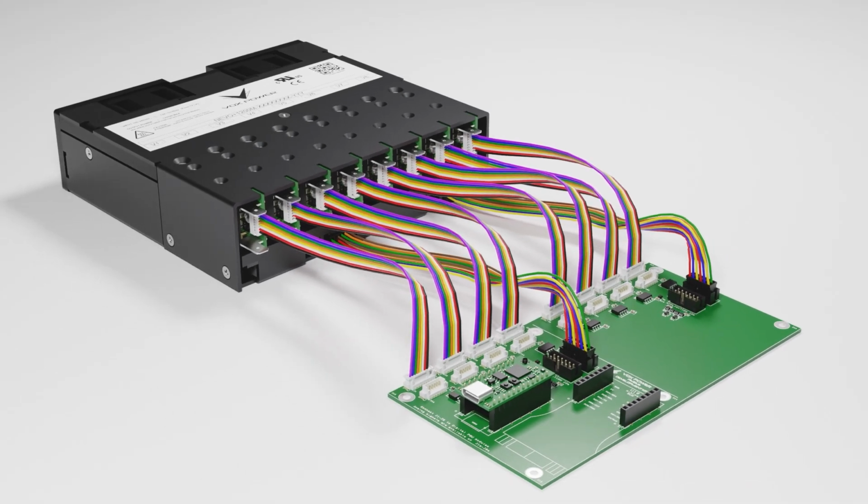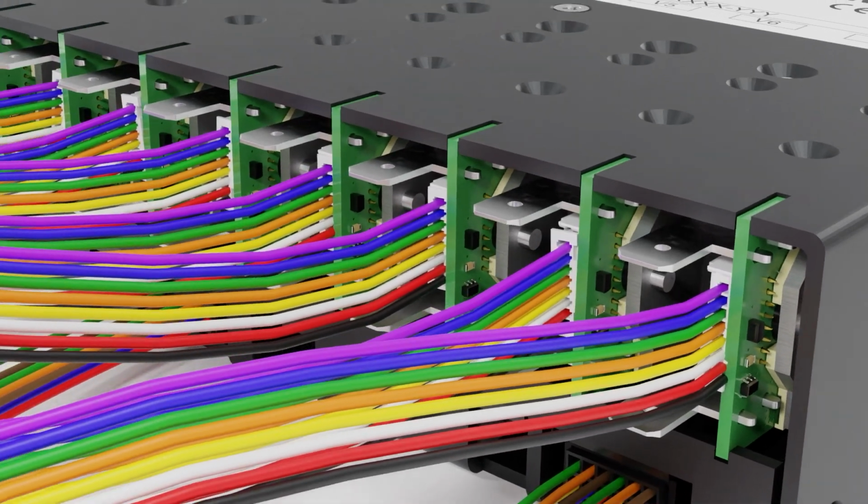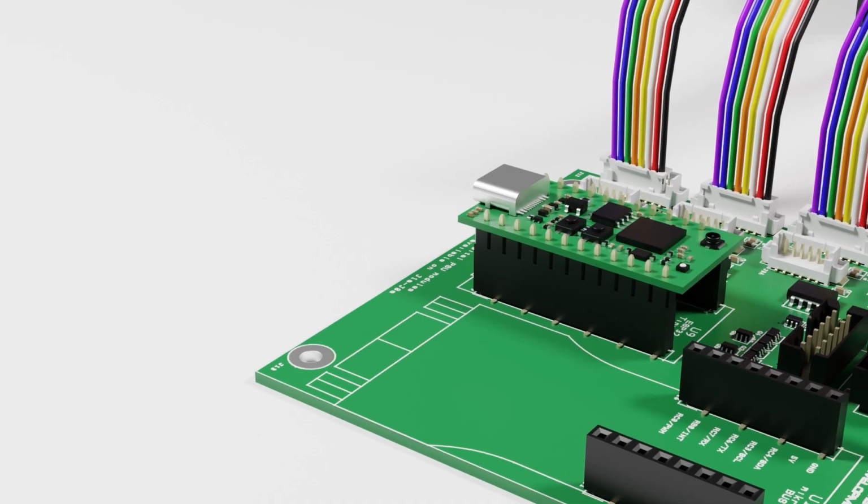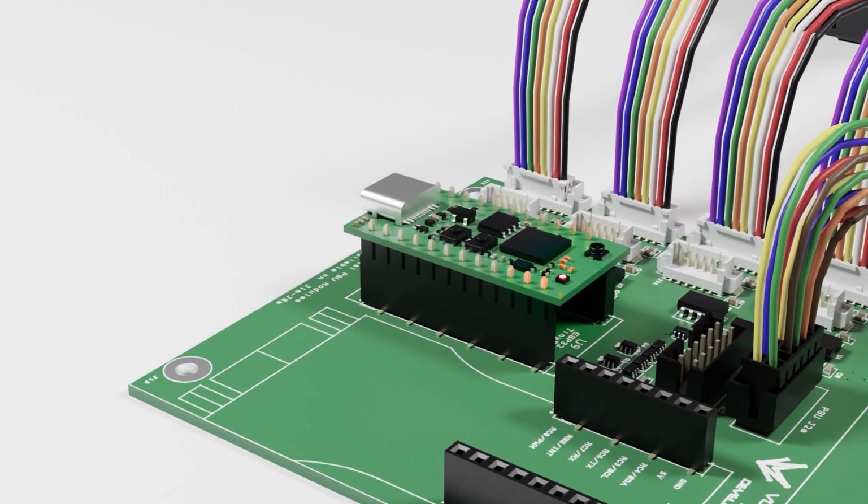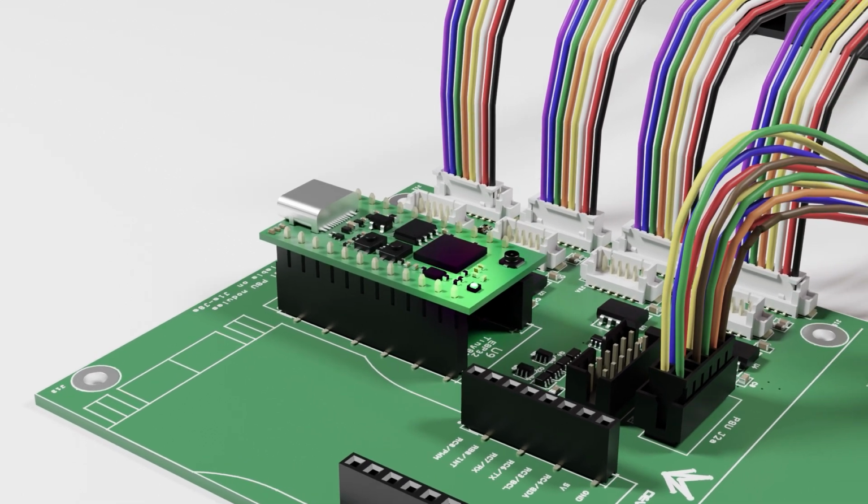With the NEVO unit and output modules connected to the DevKit, power up the NEVO unit. When the DevKit is powering on, a red LED will show initially on the DevKit. This indicates that the DevKit is booting and scanning to identify the modules in each slot of the main NEVO power supply. Once the boot and scan is complete, the LED will light up green.